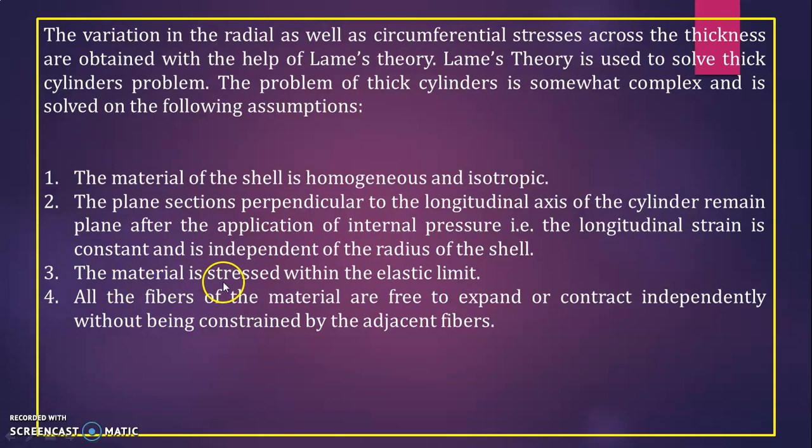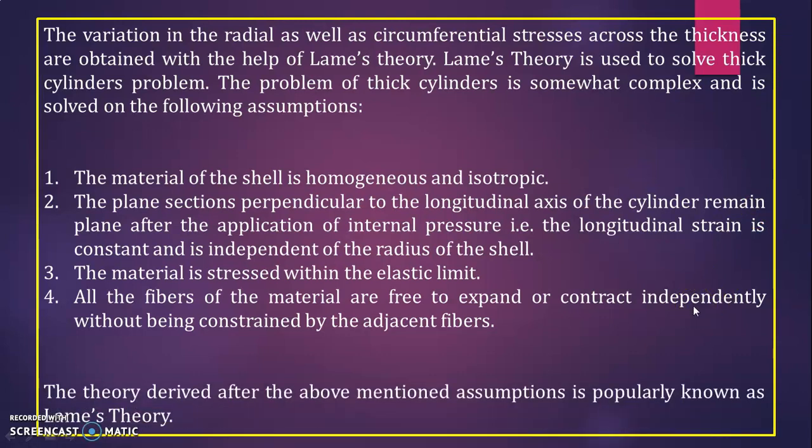Third, the material is stressed within the elastic limit, so it should obey Hooke's law. Hooke's law says stress is directly proportional to strain within the elastic limit. Then the last one is that all the fibers of the material are free to expand or contract independently without being constrained by the adjacent fibers. The theory derived after the above mentioned assumptions is popularly known as Lame's theory, so thick cylinder problems are solved using Lame's theory.